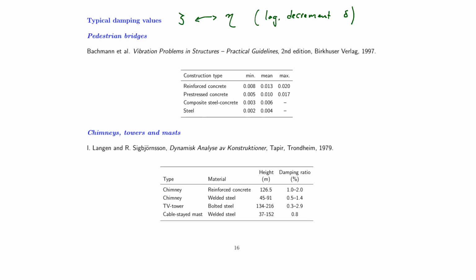So there are many measures that can be used to express damping, and I've too many times seen a loss in translation between professionals discussing damping, not really considering, for instance, the 2 pi factor between the logarithmic decrement and the viscous parameter, or the 1/2 that appears between the damping ratio and the loss factor at resonance.